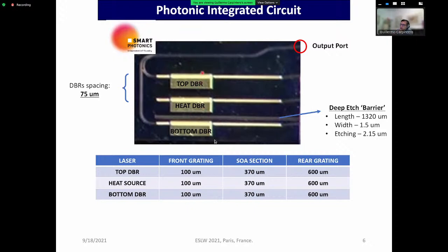But when you use it, you can increase the thermal conductivity of the lasers to the sinks to reduce the sensitivity of the lasers, but the thermal crosstalk between the components on the chip is always high because they are sharing the same substrate. And this is what we want to avoid, the thermal crosstalk. The sensitivity of each of the components we will have to address by increasing the conductivity towards the substrate, to the sink in the Peltier. But the interaction between components is something that happens within the chip, and that's why we need to find ways to increase the thermal resistance between components.